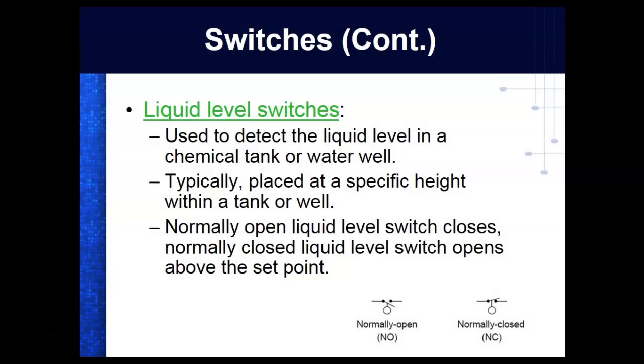A liquid level. Where do we have a liquid level sensor in our cars? On gas, yeah. It's the one that comes on that says you need to add fuel. So we have an analog sensor that tells us the amount, but sooner or later, if we let it get down, it pops up and says so. That would be a digital sensor like this, and it's technically nothing but a float like this.